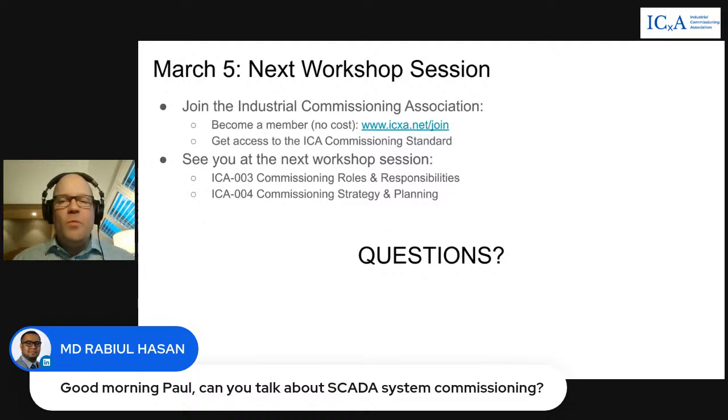On projects I've worked on, we've gone through all of our integrated factory acceptance testing 2 years prior to the in-service date to prove that these systems actually work before they arrive at site. And that makes on-site testing so much easier and reduces so much risk on projects to know that the equipment being shipped to site actually works. So then we're really only just checking for wiring errors and making sure that everything is terminated correctly, because we know all the cubicles work in advance. So that's my best advice on SCADA system commissioning: plan your projects during your project concept and FEED stages so that that integration is done in the factory, so these complex control and protection systems actually function before they get to site.